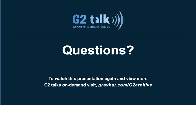Yes, Greg, that's a great question. You can definitely use your iPad to do that. With the PLC, we have a couple different ways to remotely monitor or remotely interact with them. You have your web servers, which of course has pre-configured functionality, and then you have your web visualizations, which are your HTML5 web pages that you're able to set up within the Machine Expert software. Both of those can be set up in a way that you're able to, with an IP address, with the right level of